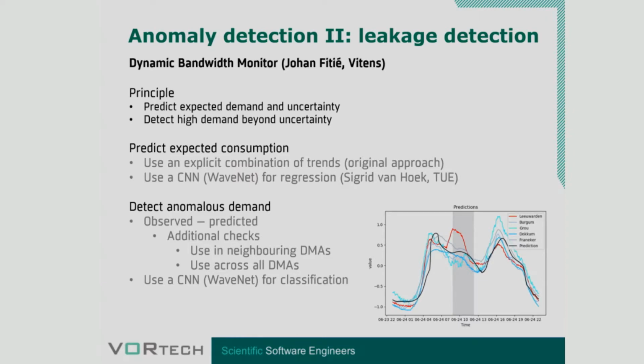And another thing that we added was that you can also look across many DMAs, and if you see a high demand in all the DMAs, then it's probably not a leakage because it couldn't be leaking in all the DMAs at the same moment. Very simple, but it works nicely.